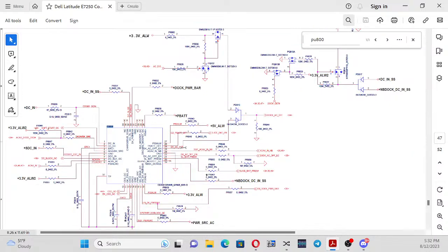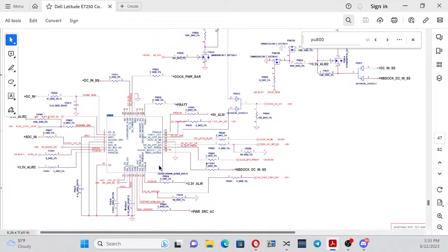So you can see from here you get your plus 5 volts always. That's the enable signal for the 3.3. D power bad, DCE, SDA, all those signals which I was showing you, which are going to those controllers, are coming from here. They're generated from this chip. So what I realized is that this has been removed and replaced before I got here, because it clearly has got some scratches on it.